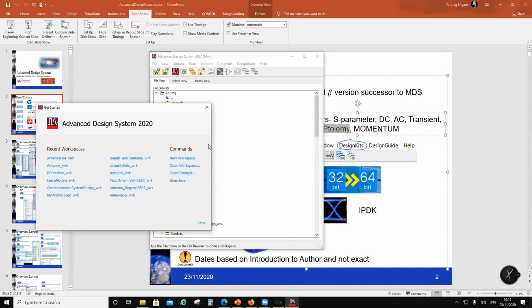Okay, like for example, here in ADS, they have something called harmonic balance, right? Which is a Volterra series technique. Okay, what is a Volterra series technique? Very easily, okay. Whenever there is a system, it has a transfer function, and your signal is convolved with the transfer function to get the output. Now, very simply put, you can always interchange signal and transfer function, because it's just a convolution between two signals, right? That means that a system transfer function is nothing but a second signal, right? So you are performing convolution between two signals, right?